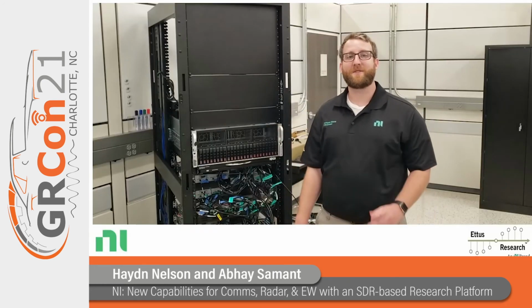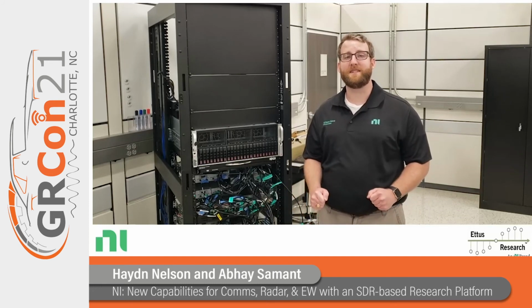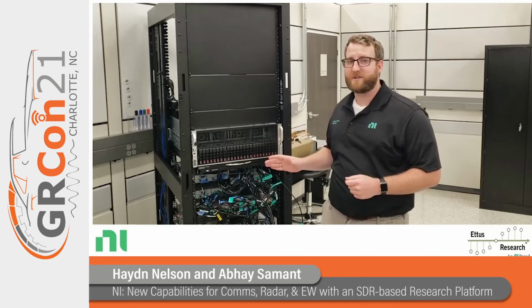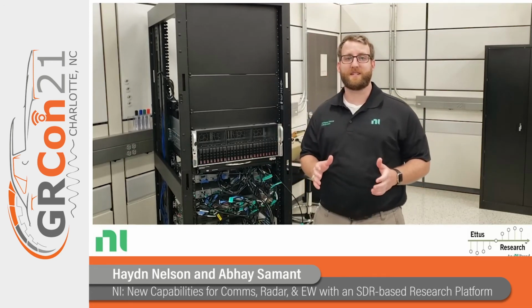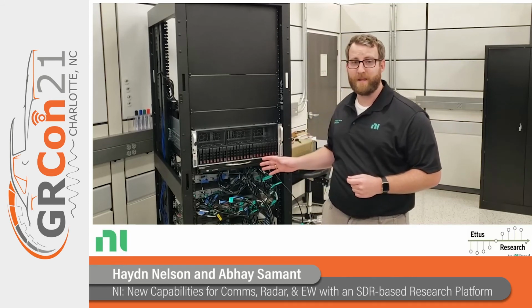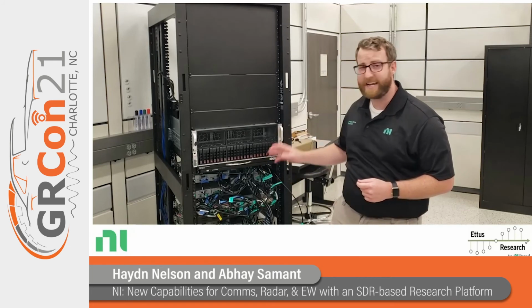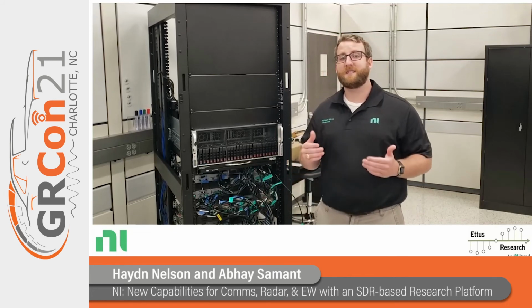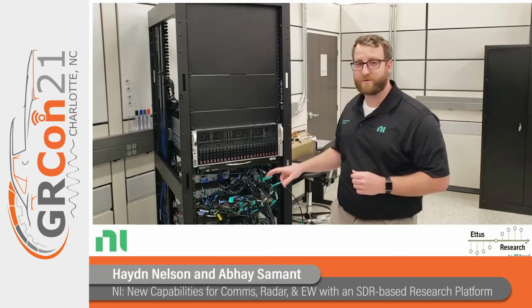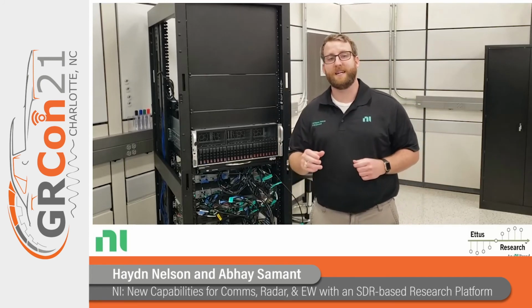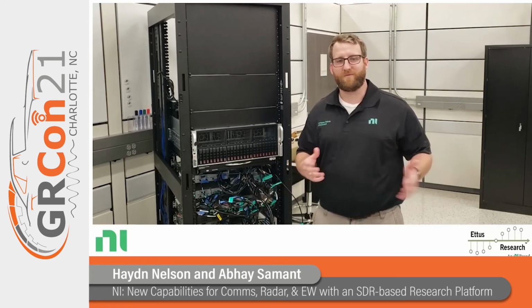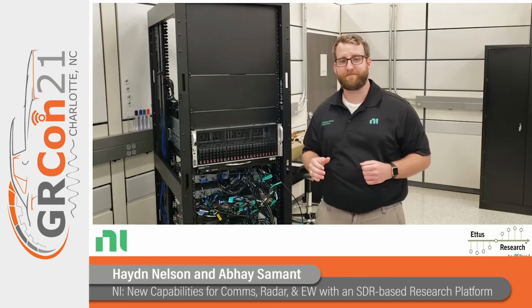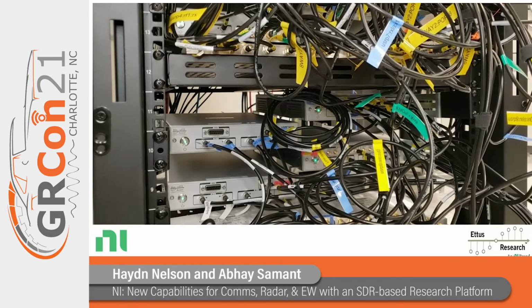Hi, I'm Jovian Wysocki, Systems R&D Engineer for NI's Aerospace and Defense Business Unit. Today, I'd like to briefly walk through an instance of our RF multi-channel research testbed. This instance of our reference architecture is built on the USRP hardware driver using USRP N321s and N320s. This system here is a 32-channel system composed of 16 USRPs. It's a combination of N320s and N321s all hooked up to 10 gig connections. It's more than just putting radios in a rack. We've specified the topology for LO and clock distribution. You can see here, we have a lot of wires. It can get kind of messy.